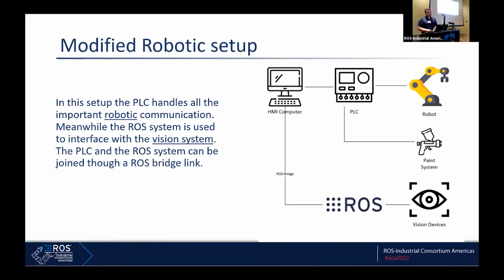So with ROS and with ROS Bridge, we're able to take data that's a little bit more complex than normal PLC bits and bytes. An example would be Velodyne LiDAR data. LiDAR data isn't something that you can really just pick up from a PLC. It's a little bit more complex. So without having to go out and build our own UDP drivers to drink in point cloud data, we went ahead and used ROS, leveraged its drivers that some people had already integrated, and we could keep our setup a little bit cleaner.